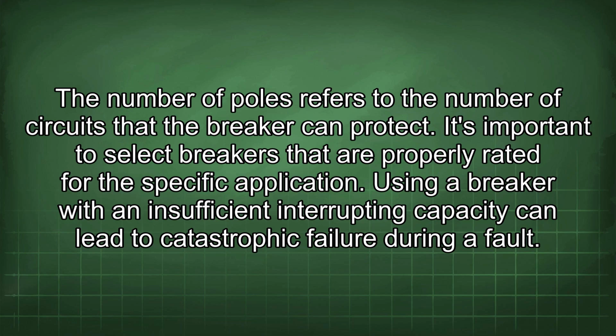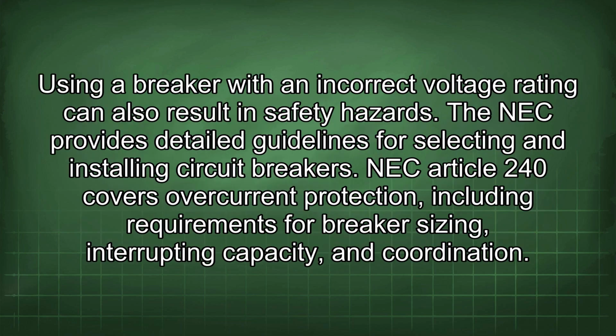It's important to select breakers that are properly rated for the specific application. Using a breaker with an insufficient interrupting capacity can lead to catastrophic failure during a fault. Using a breaker with an incorrect voltage rating can also result in safety hazards. The NEC provides detailed guidelines for selecting and installing circuit breakers.